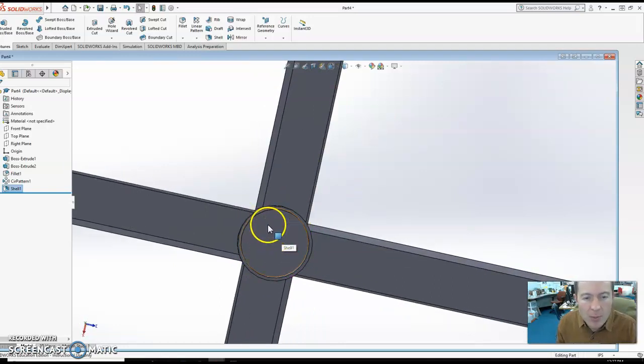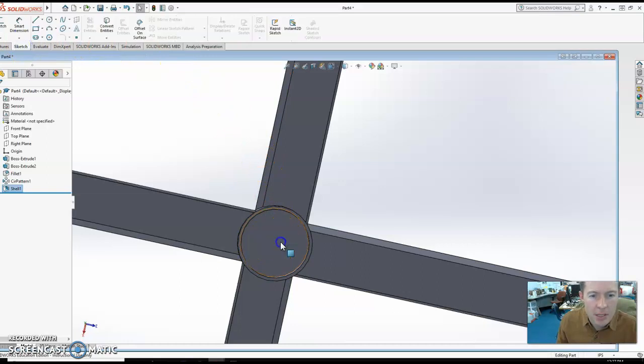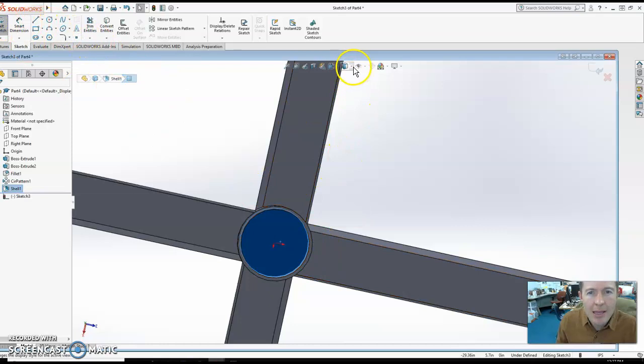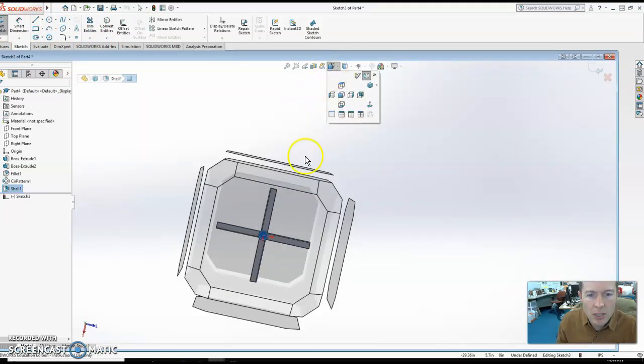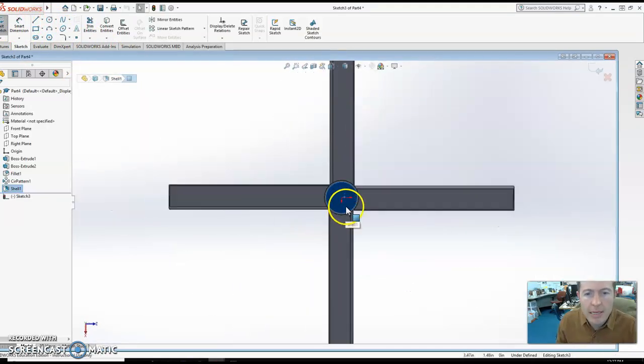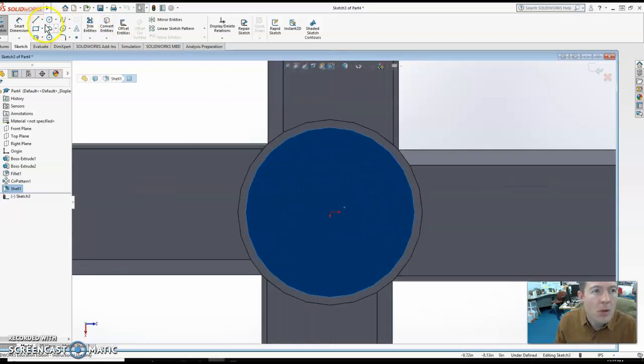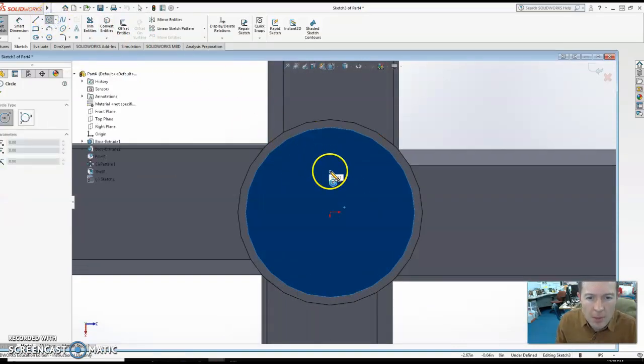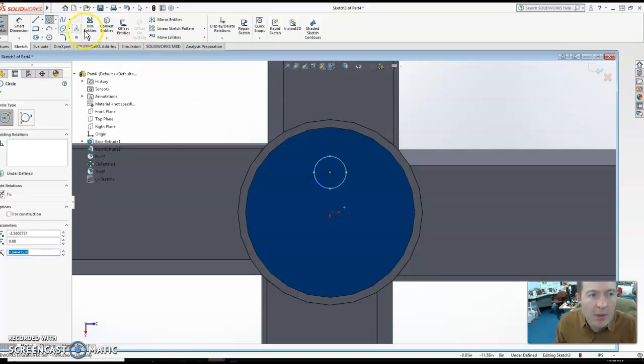Now for our propeller, we're probably going to want some bolts on the inside of this. So let me put a couple holes here for a couple of these bolts to go into. For that, let's start a sketch here. I like having a head-on view, so I'm going to click here, click this. Now I have a head-on view. So let me set a little circle up here. Notice it kind of auto-fills in. It shows me that I'm at the center there. So there we have that hole.